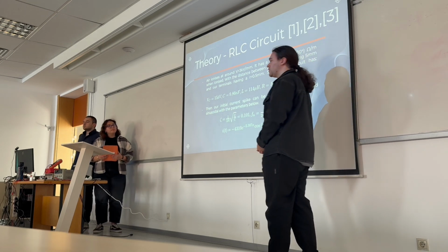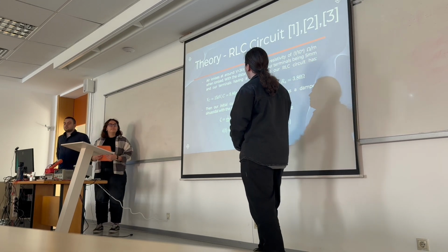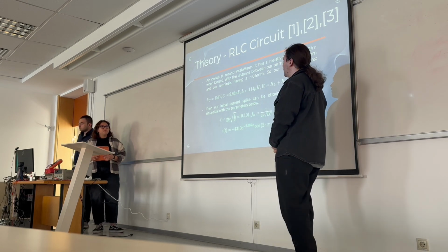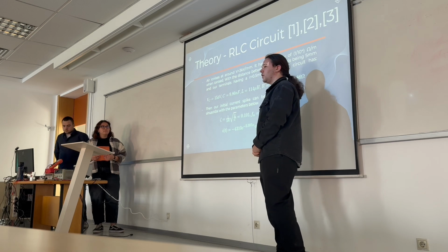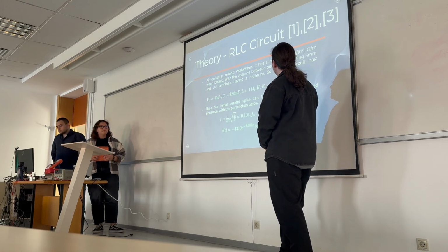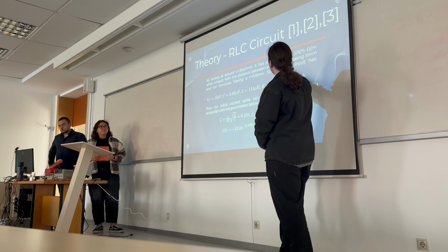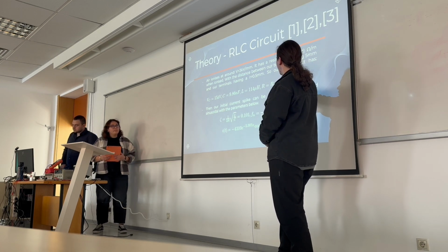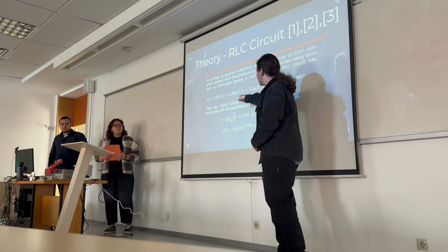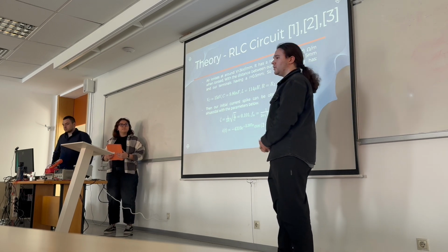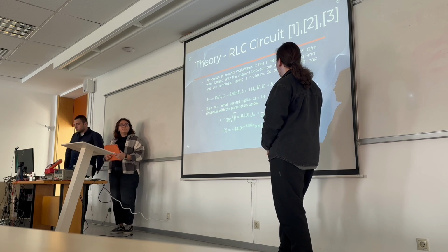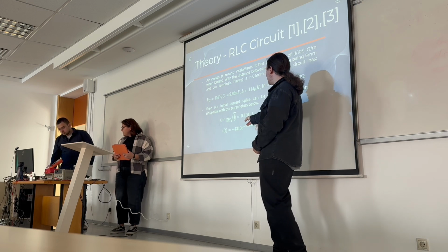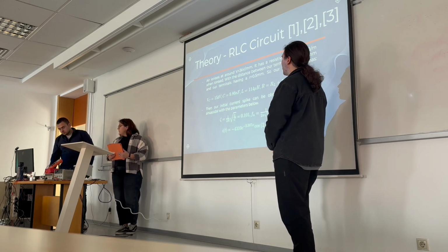Finally, to obtain this current, we will use an RLC circuit. Air ionizes at around 3 kilovolts per millimeter, and our spark gap is 5 millimeters in length. So we will need 15 kilovolts in our capacitor. And the resistance of the circuit can be calculated from the resistivity and the terminal width and the length as 3.86 ohms, along with the resistance of our inductor, and our capacitances and inductances are as shown. Using the transfer function from the previous slide, we can obtain the current as a function of time like this, with damping ratio 0.101 and frequency 150 kilohertz.